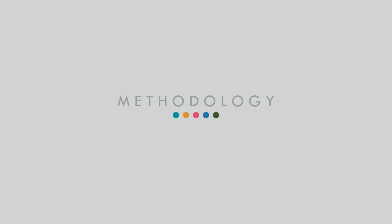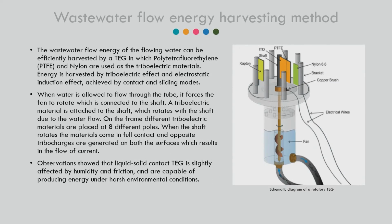For the methodology, we need to review the methods that can be used in the triboelectric generator. First, the wastewater flow energy harvesting method. The energy of flowing wastewater can be efficiently harvested by a triboelectric generator in which PTFE and nylon are used as the triboelectric materials. Energy is harvested by the triboelectric effect and electrostatic induction effect achieved by contact and sliding mode.